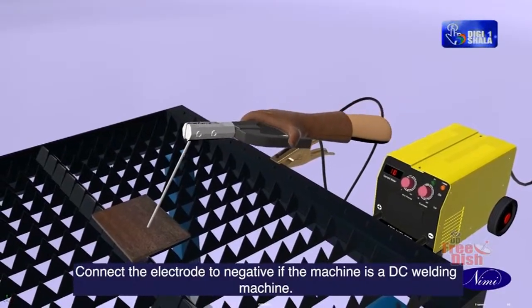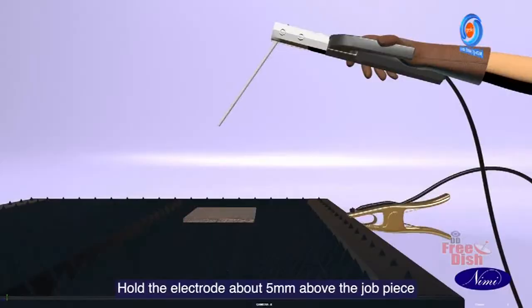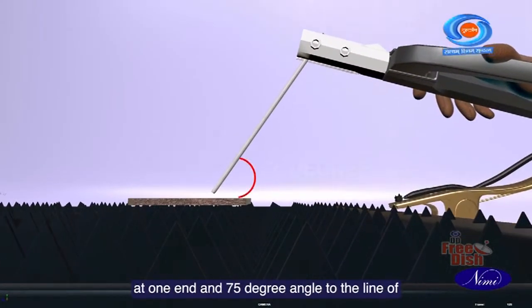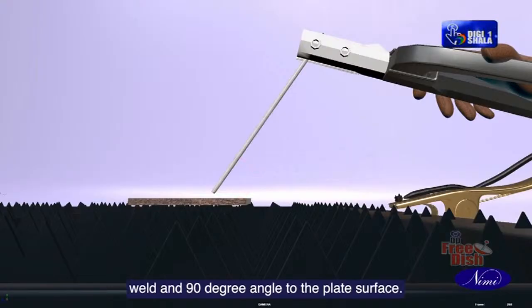Connect the electrode to negative if the machine is a DC welding machine. Hold the electrode about 5 mm above the job piece at one end and 75-degree angle to the line of weld and 90-degree angle to the plate surface.